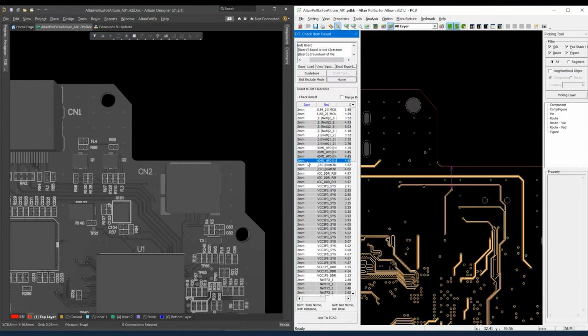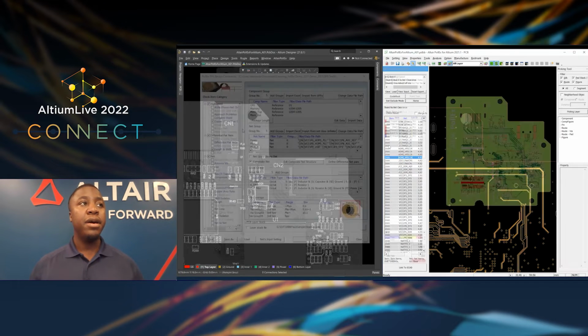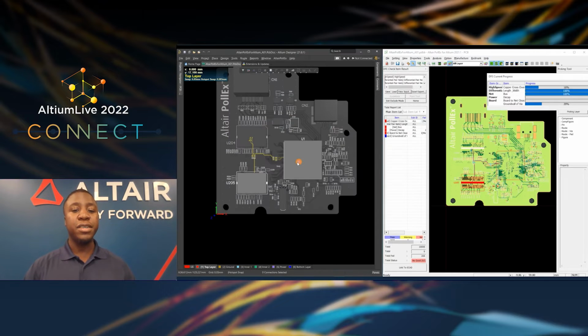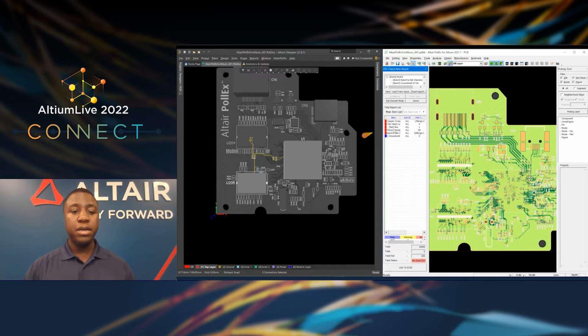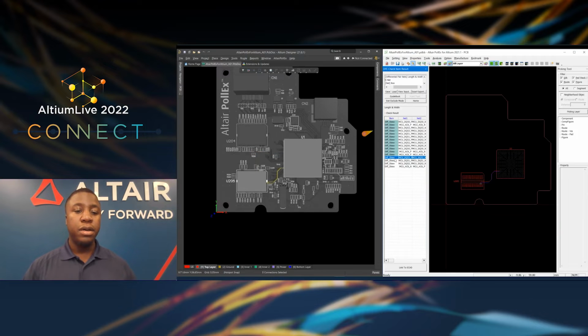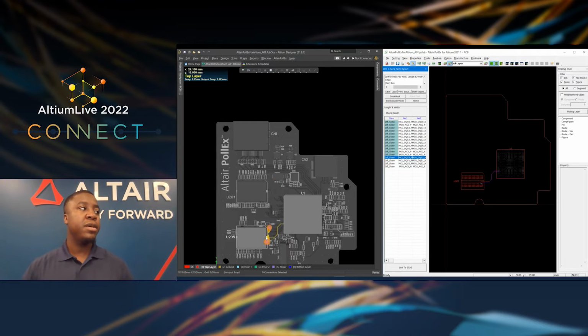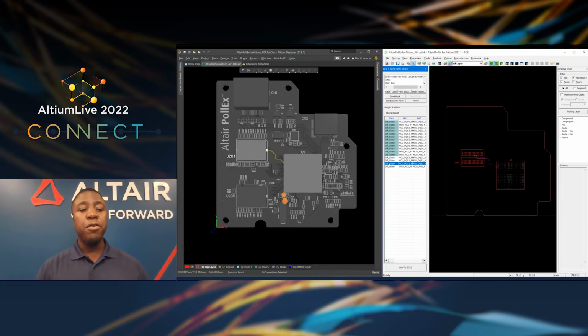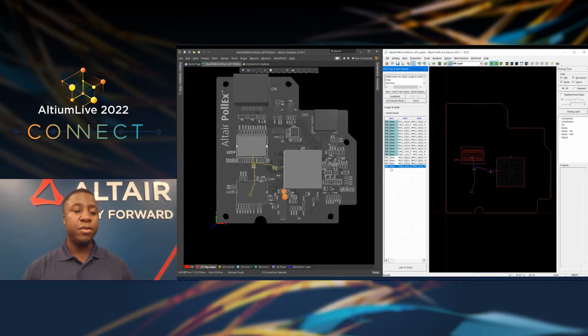I'm able to do this for multiple parts of the PCB. And finally, we can check some of our differential pairs and look at the length and width of them. So we run the verification. And we're able to look at, again, certain areas that may be a problem while cross-probing into our Altium solution, understanding more and adding more detail into the full overall area of concern.